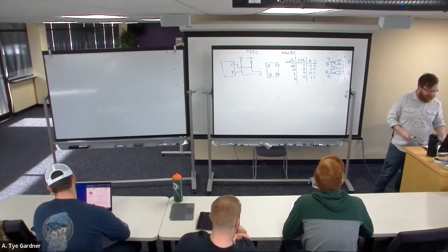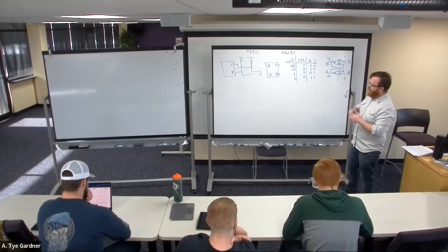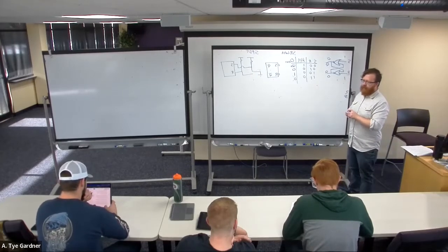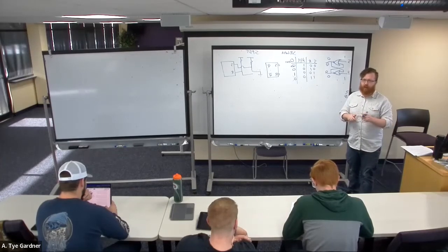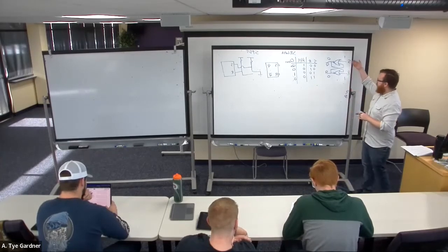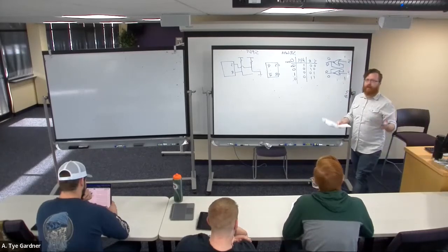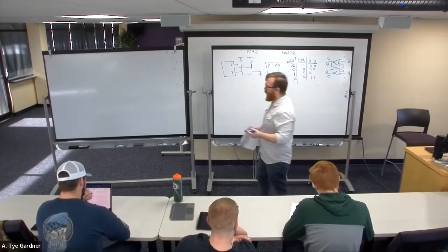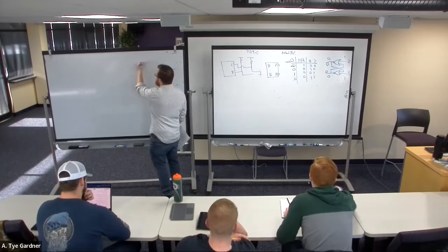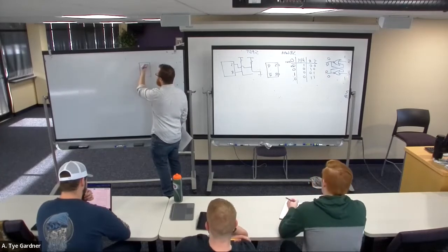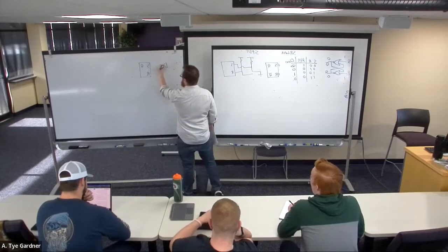So the next step in complexity is, well, it's nice to have set and reset, but it's also nice to have something that's just going to hold on to data, right? Some value of a data signal. We have to keep track of a set and reset. What do we do if we only want to keep track of what was the output of my signal last? What was my last signal? Well, we do that with something called a D latch that starts out with an SR latch. And we just add a little bit of circuitry to it.